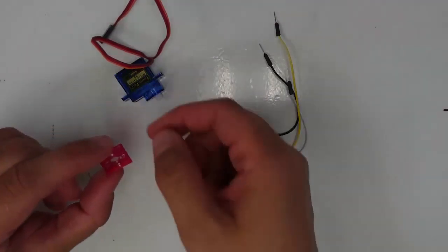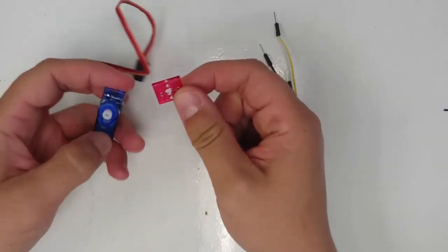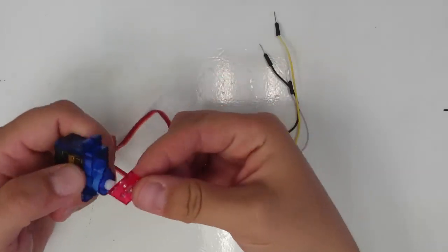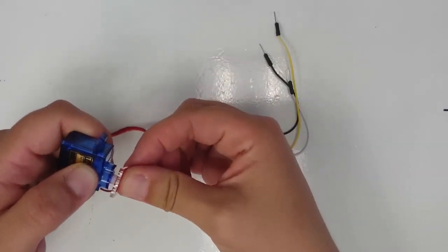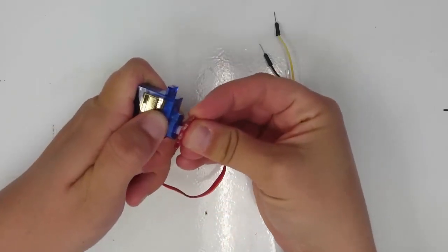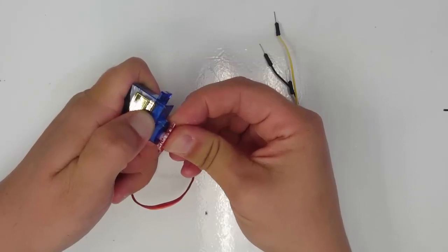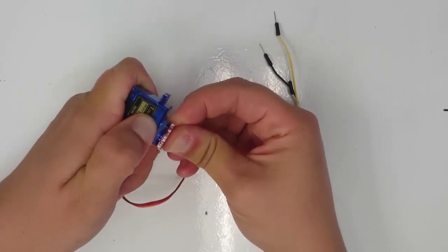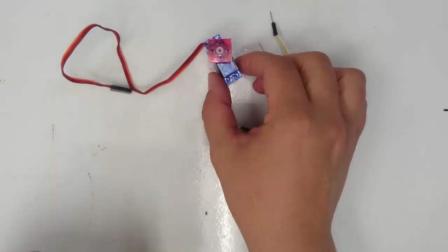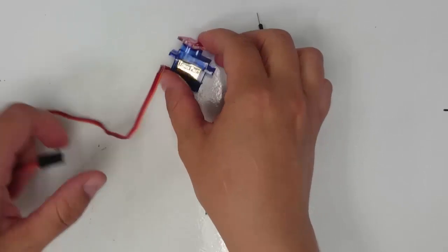The first thing I'm going to do is press this servo horn onto the servo. Now I'm going to do this very carefully. The horn goes on one way much easier than the other way. So if you're trying to press the servo horn onto the servo and it's going on really hard, just pull the servo horn off, flip it over, and press it on the other way. There we go. Having the servo horn on will help us to see what angle the servo is at better. Now,